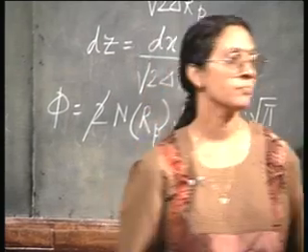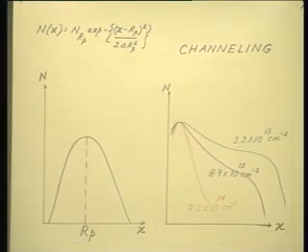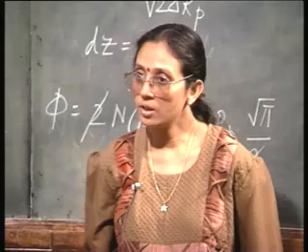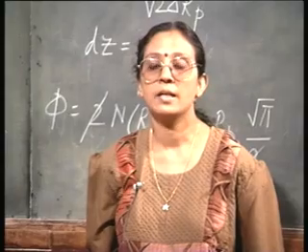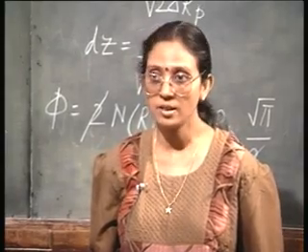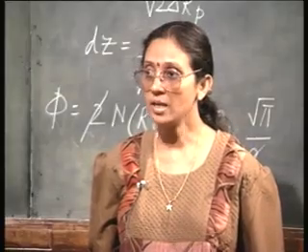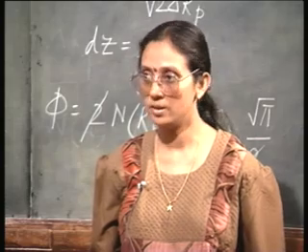On the other hand, when your dose is much smaller and the ion beam is directed along a major crystallographic axis, that is 110, then the disorder is less, the target resembles not an amorphous target but a crystalline target, and it is possible for the ion beams to find the channel and move forward through a much greater distance.